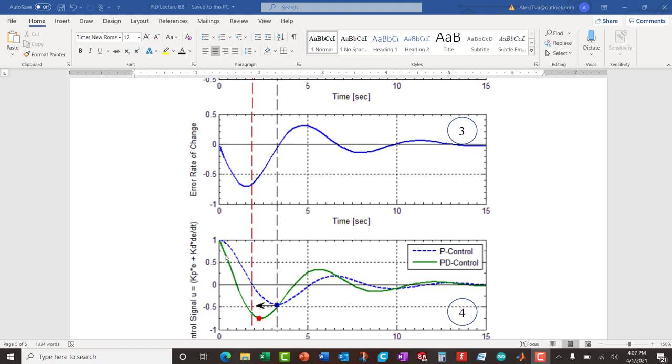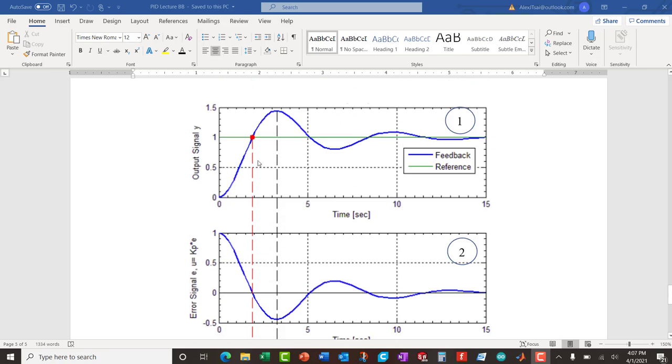Now, if we were to plot the ball response with this voltage, the green voltage, we would see that this bump, that overshoot, would be attenuated. So we would have less of an overshoot, and this bouncing back and forth, the time that it finalizes, that's called the settling time, would be much shorter. Okay, so essentially we are improving our transient response. We're making it faster and more damped.